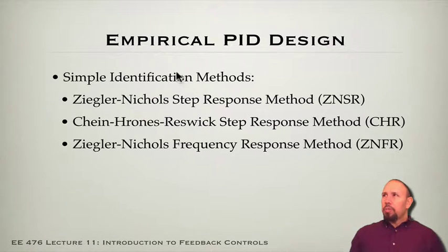There are also empirical methods for doing PID design, where we do a simple experiment. Two of these methods involve a step response. You apply a step to the system, look at the output, and based on features of the output, you have a design for the controller. These design methods are fairly straightforward, and again, I talked about these in E314, so I'm not going to talk much about them here. There's also a frequency response method that can be used. Again, this involves another experiment.